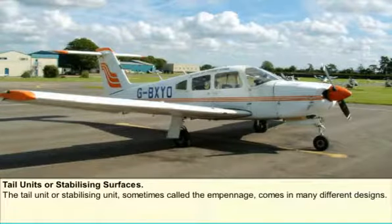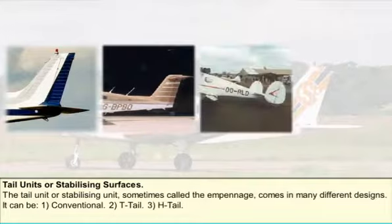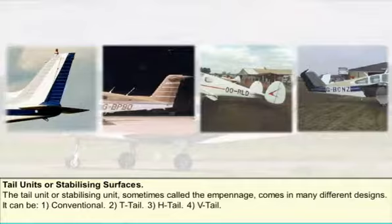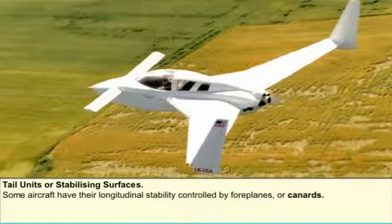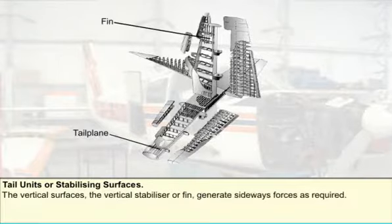The tail unit, or stabilizing unit, sometimes called the empennage, comes in many different designs. It can be conventional, T-tail, H-tail, or V-tail. Some aircraft have their longitudinal stability and control provided by foreplanes, canards. The horizontal surfaces, which are known as the tailplane or horizontal stabilizer, provide longitudinal stability by generating upwards or downwards forces as required. The vertical surfaces, the vertical stabilizer or fin, generate sideways forces as required.